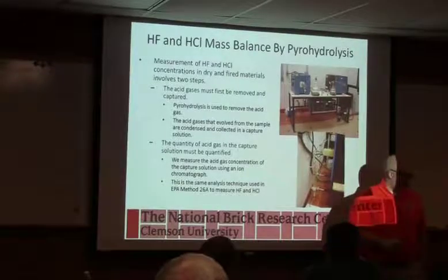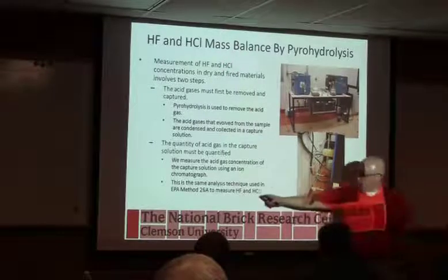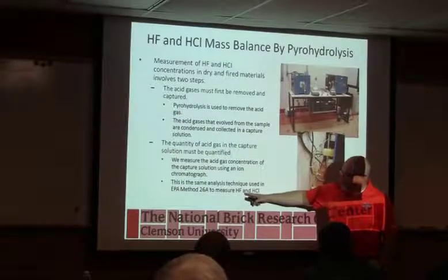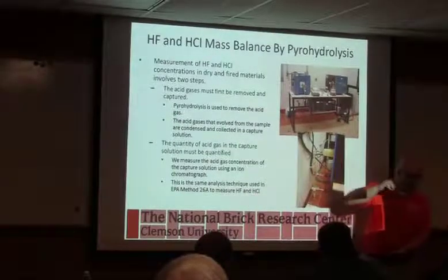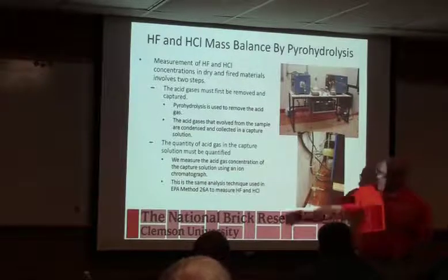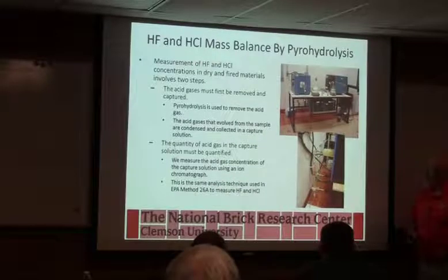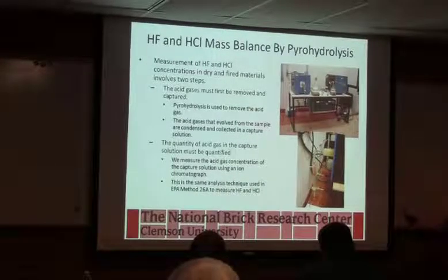Yeah. Okay, so that's a whole art in and of itself. But basically, depending on which method they did, at the end of that, to measure the fluorine and chlorine in those glass things, the impingers at the end of the train, they use the same method. So we take the dry material and the fired material, and we measure the fluorine and the chlorine and assume the difference is what went up the stack.